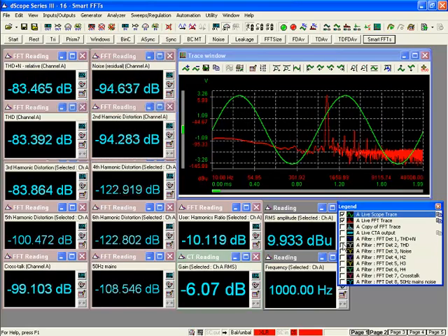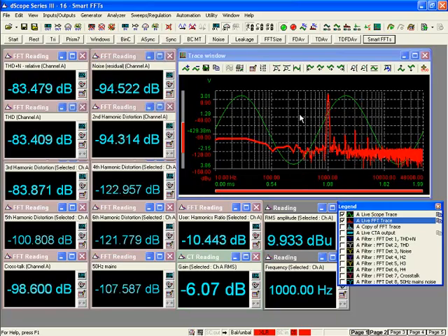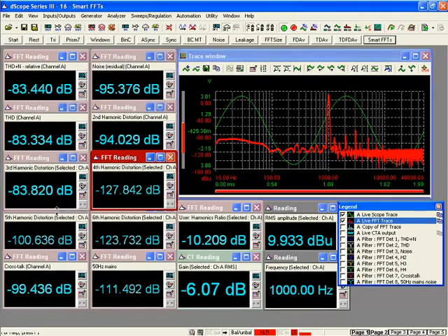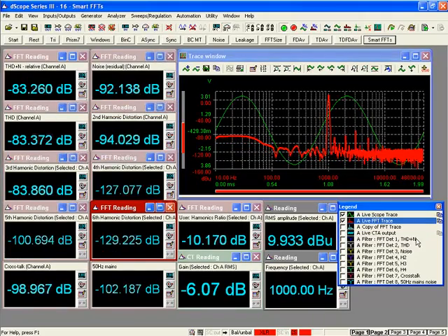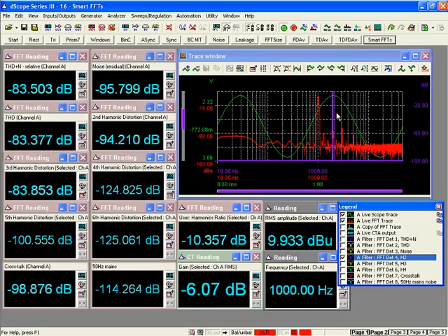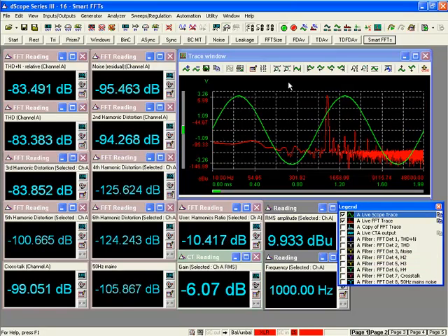And there's no way we could have come up with that numerical analysis from just simply looking at this FFT data. And beyond that, we can isolate the second harmonic, the third, the fourth, the fifth, and the sixth, and we can go on. I'll just show you the second harmonic, for example. That's just simply giving us a brick wall notch filter to analyse the second harmonic distortion amplitude.